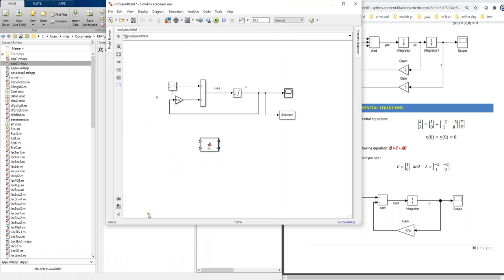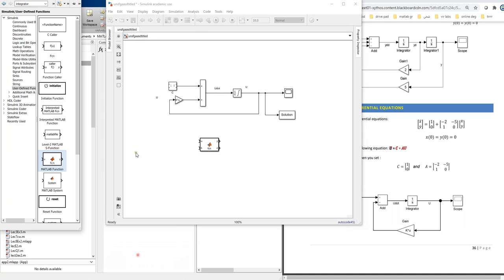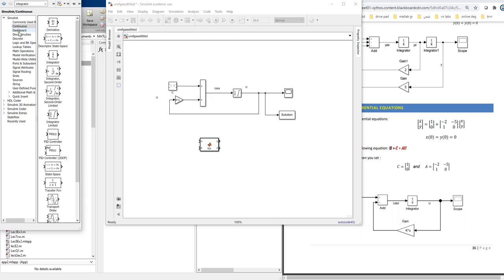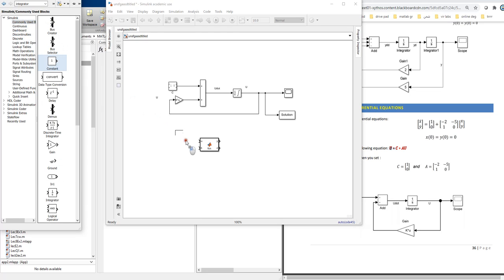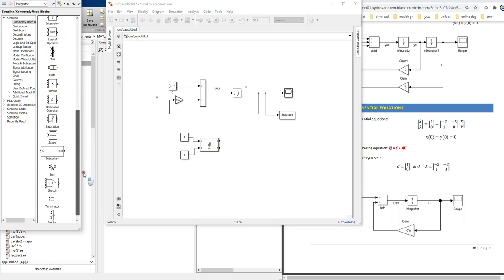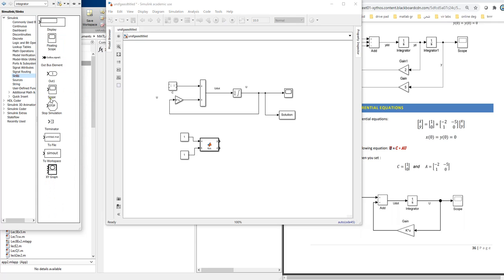So again, like this, connect this one as an example. Let me bring a constant here, and Control C, Control V, another constant. Connect this one to here, connect this one to here, and it should give us two outputs. We can show them using the sink. We have here display to display a value. Connect this one. This is the first one. Control C, Control V. The second one. Display both of them.